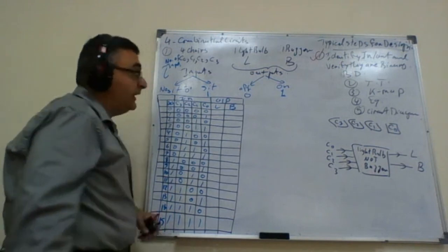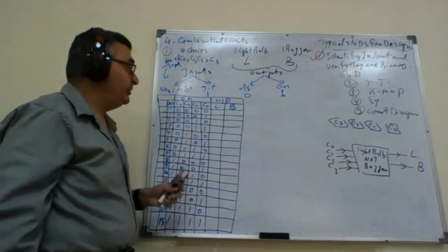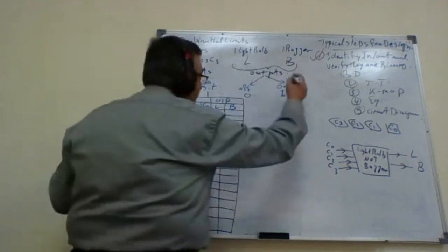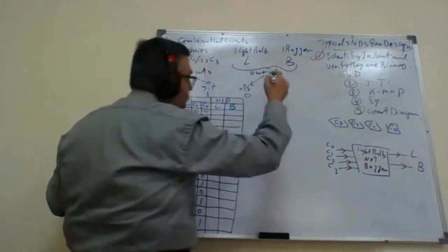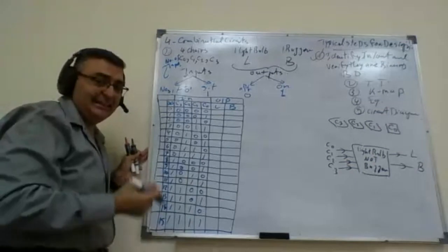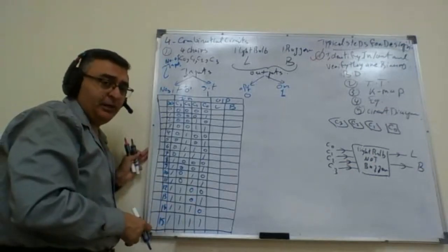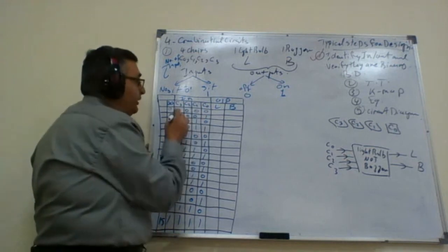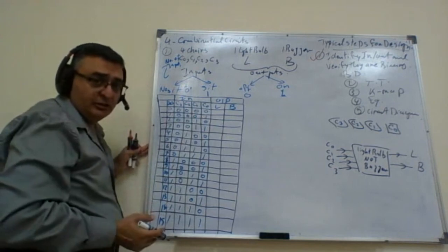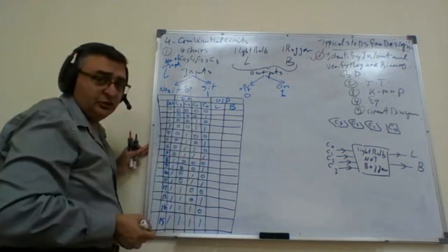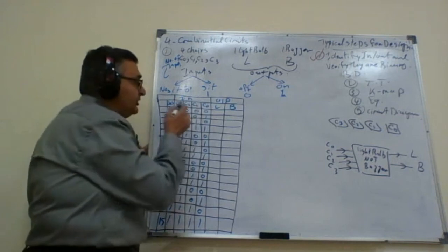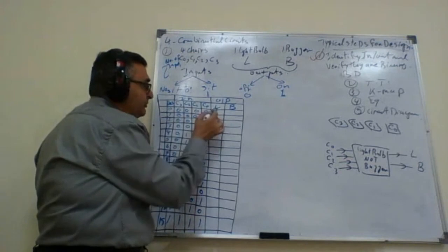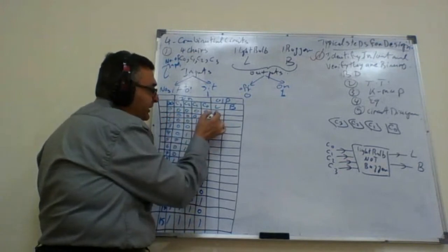Okay? All right. Now, from the relationship that he mentions between the light bulb and the chairs, L, which is the light bulb, will go on if 2 or more students are sitting next to each other, as the problem explained. Go back to the slides if you would like to confirm that. Since we give the value 0 for no student sitting on the chairs, 1 for a student sitting on the chairs, we can easily identify whether 2 students are sitting next to each other or not. Based on this definition, all 0s means no student sitting on the chairs. That means L should be 0.